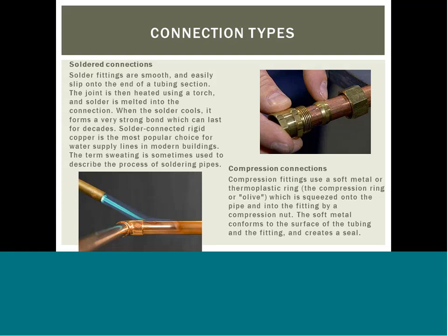In situations where many connections must be made at once, such as plumbing of a new building, solder offers much quicker and much less expensive joinery than compression or flare fittings. The term sweating is sometimes used to describe the process of soldering pipes.